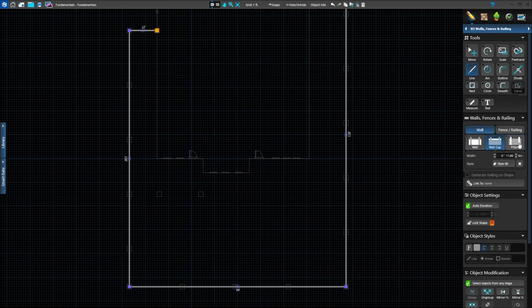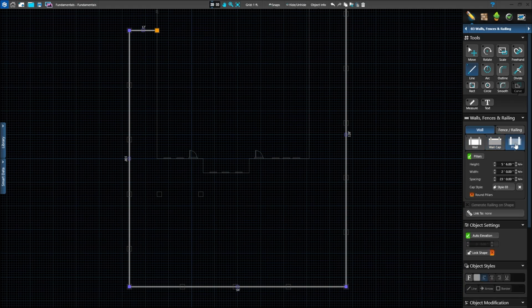Next, we'll talk about pillars. Go ahead and click on pillars. If they don't have pillars at all, you can just turn that toggle off and the pillars are all gone. If they do have pillars, with the pillar setting turned on, you can look at the height of the pillars, the width of the pillars, the spacing of the pillars is sometimes pretty important. If you want more pillars, you decrease the value in the spacing. If you want fewer pillars, you increase the value in the spacing. Let's take a look at that in 3D.